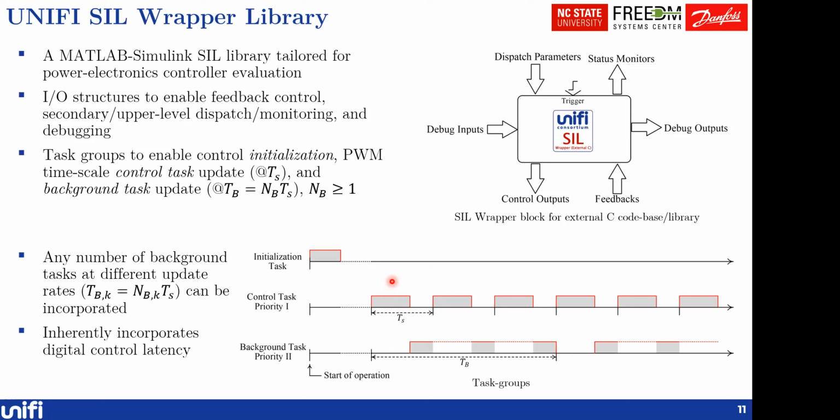One more thing to note here is that when you implement your control in a discrete time way, there is always a control implementation lag. The way this block is implemented, it will enforce that control lag is always there. You don't need to worry about explicitly emulating that in your simulation. The block will always do that by itself.